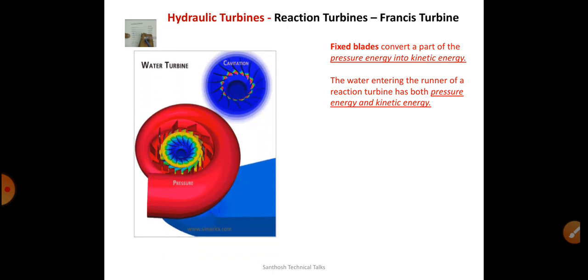So here it is. In the Francis turbine, the main problem is cavitation. Cavitation means a conversion of the jet of water into water vapor because of the pressure difference. Here, the cavitation is caused by vapor pressure. This vapor is not at all produced by means of temperature, it is produced by means of the variation of pressure. So the cavitation is a problem here.